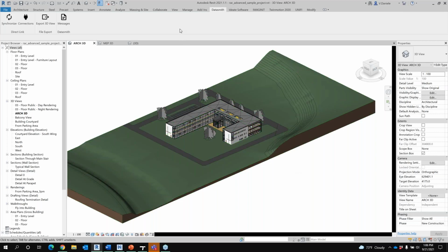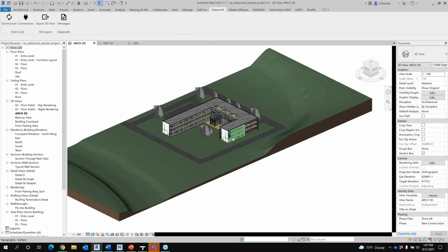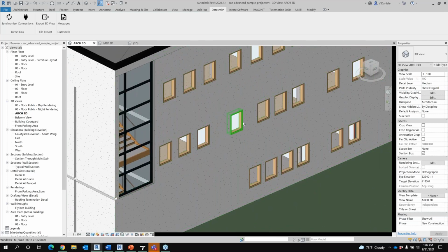And a number of our customers reached out, or still reach out to us, saying that they export their Revit models and things aren't there that should be there. And then I'll go through and troubleshoot, and I can't figure out why certain objects are gone; there's no rhyme or reason. The one thing I could maybe think of is that a glazing or glass material was causing issues, but it would only do it on certain families. So you could have two windows and one window would be gone, even though they would be the same window type. It was just very odd behavior.